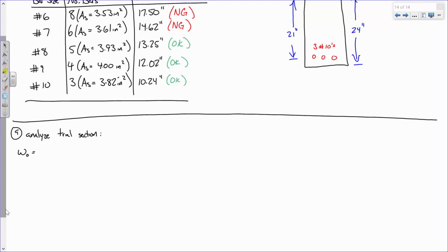You need to remember that because we're going to be doing that quite a bit in here. So gamma times B times H. We're going to do it in kips. That's 0.15 kips per cubic foot. Remember, normal concrete, we're saying weighs 150 pounds per cubic foot or 0.15 kips per cubic foot. And then instead of those assumed dimensions, we're using the actual dimensions of the beam, 14 inches and 24 inches. Now, do I have something I need to do here? Divide by 144, because 1 foot squared is 144 inches squared.